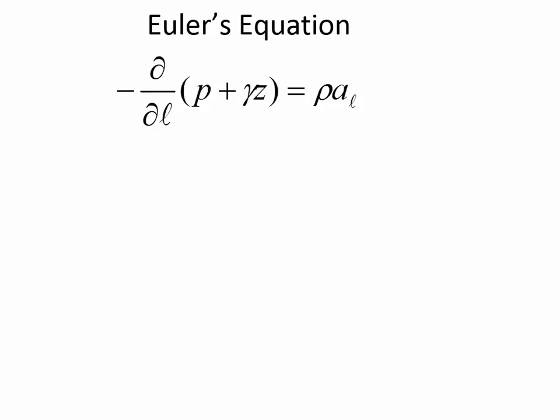We won't consider or apply Euler's equation in 3 dimensions simultaneously, although it would work out just fine if we did. And so when we apply Euler's equation, if there is acceleration at the same time in 2 different directions, that means that we have to apply Euler's equation one direction at a time. And that's the first thing I'll say about it.